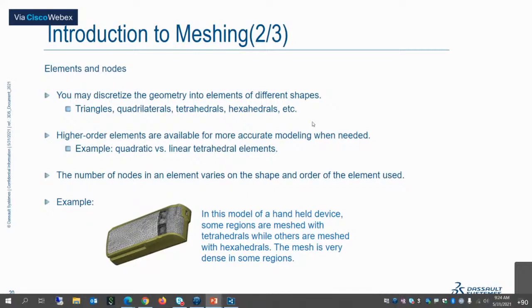Now in meshing, based on the product, the mesh size and the mesh properties are different for each part in a product itself. In the image here, the mesh for the outer body is a little different, but the inner cavity has a much more detailed mesh as compared to the outer. You do this when you have a stress concentration zone, for example if you have a sharp corner in your object. Since the stress concentration would be higher there, you can define a finer mesh, and this will help you validate your results much more easily.